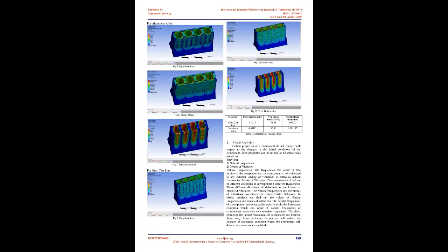Nonetheless, gray cast irons are generally weak and are prone to cracking and distortion. Because of these issues, compacted graphite iron has lately competed with gray cast iron as the choice material to produce diesel engine blocks. Figure 2 shows the BMW S54 inline 6 used in their Elite M3 car. It is interesting to note that the cylinder block for this engine is built from gray cast iron.